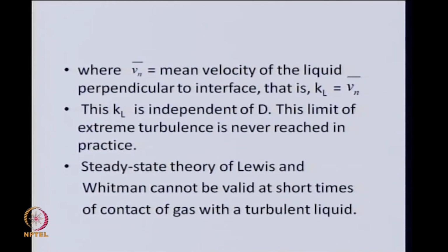Obviously, these are extremes and the Lewis-Whitman film theory will not be applicable for short times of exposure. If the gas is in contact with turbulent liquid, in all probability the liquid elements will pick up gas only for a short time. We are very unlikely to find the long times required for establishing steady state envisaged in film theory. So, film theory is much less credited today than it was in the beginning.